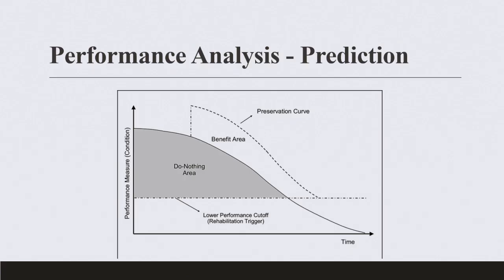So, and reactive is maintenance. So the earlier this intervention is, or the higher the condition you are on the solid line, the more likely this is a preservation. Because you cannot preserve a road that is already deteriorated, right? Preservation, the motto is the best first. Maintenance is the worst first.